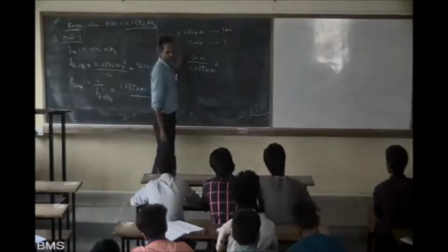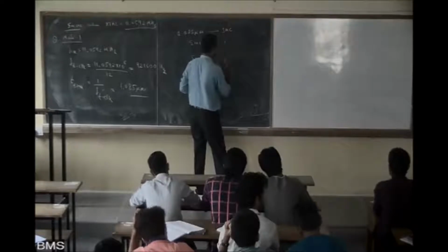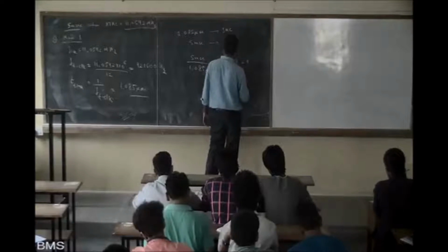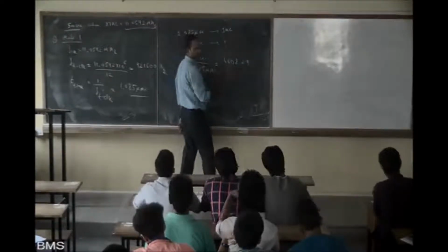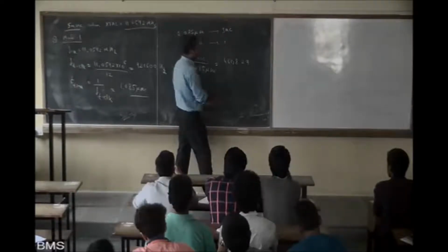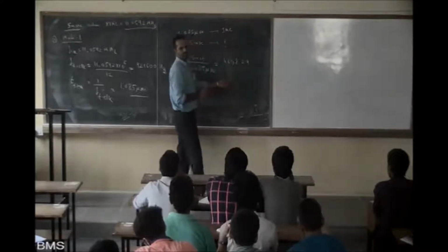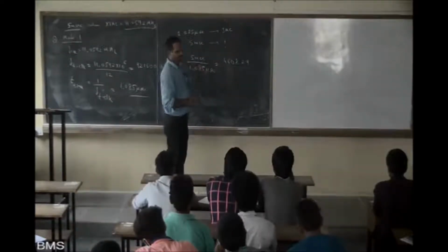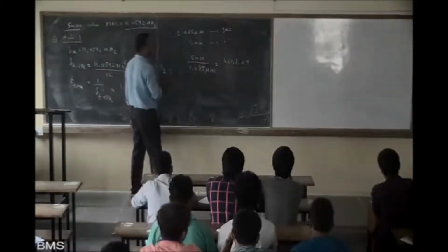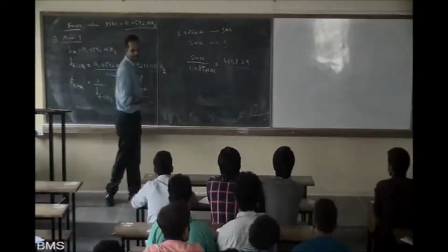What is the answer? 5 milliseconds divided by 1.085 microseconds is 4608.29. This is all in seconds. No, hold on. 4608 is the total number of counts that we wanted. Seconds will cancel, so this will be the count. Now, the problem is you have only an up counter.